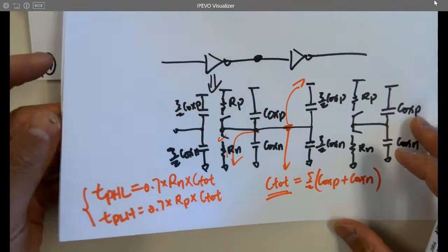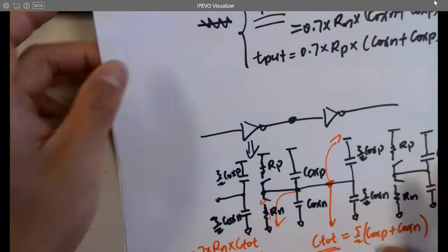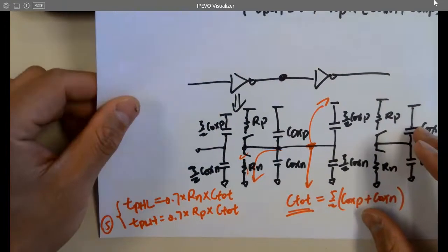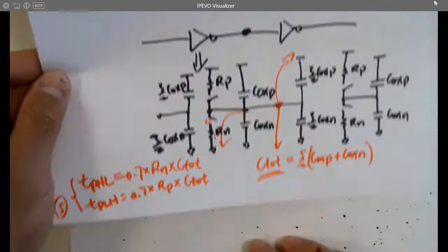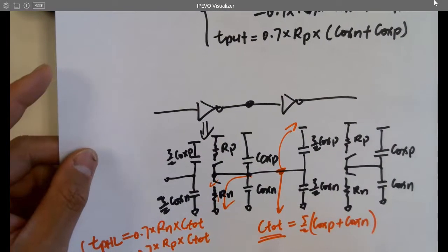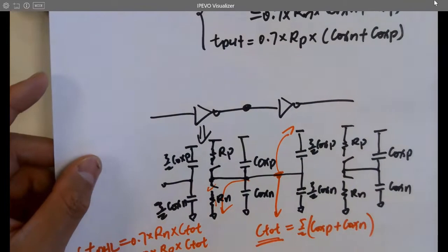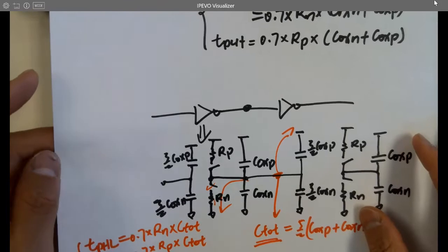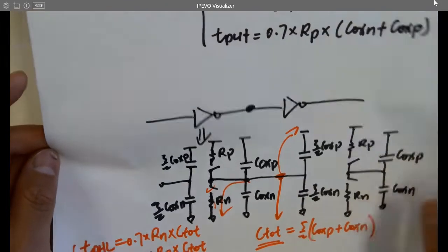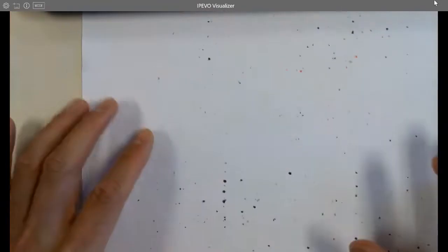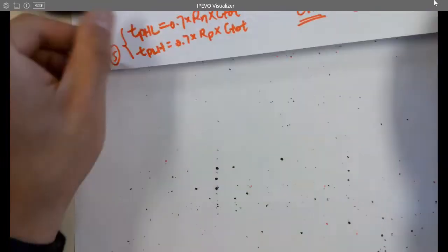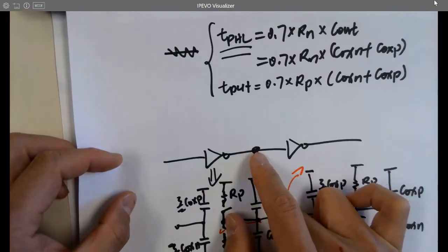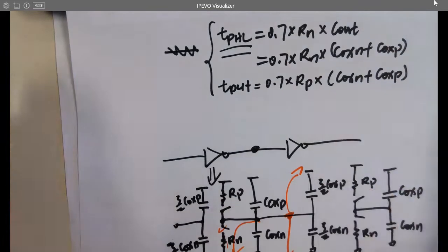You didn't do the ring oscillator? Did you wonder about why the ring oscillator oscillates? Couldn't you just put a bunch of resistors and capacitors in it on the same thing? No, you have to invert it. We are going to show why it works on Monday, and how to calculate the time delay for the specific ring oscillator. You have 7, how to calculate the time delay.